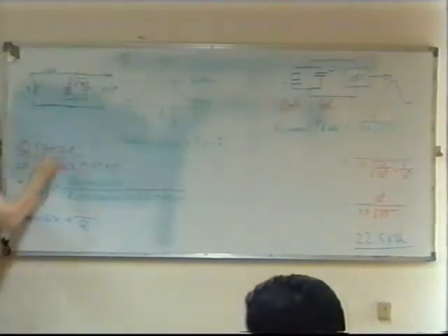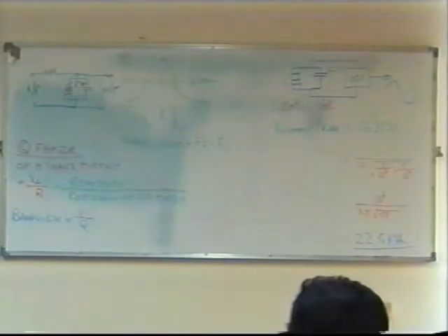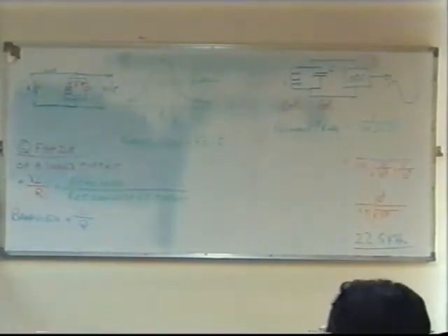It's this R which applies to any tuned circuit. So any tuned circuit at all, you can say it has a certain Q factor. That R here is not a resistor, it is resistance, of the coil of wire, capacitor, connections, perhaps losses through heat and radiation. I'll talk about that in a minute as we get on to radiating.